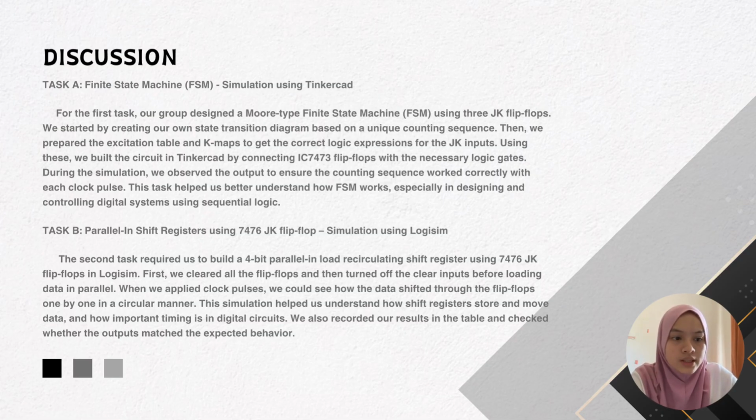When we applied the clock pulse, we could see how the data shifted through the flip-flops one by one in a circular manner. This simulation helped us to understand how shift registers store and move data, and how important timing is in digital circuits. We also recorded our results in the table in the report, noting whether the outputs match the expected behavior or not.